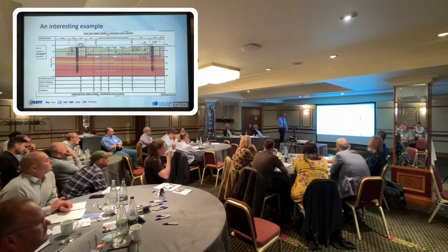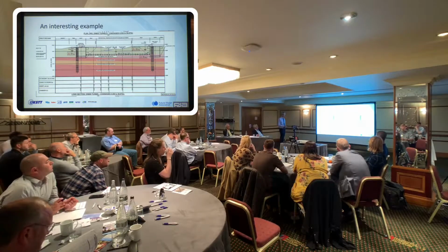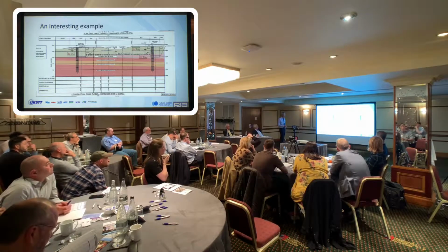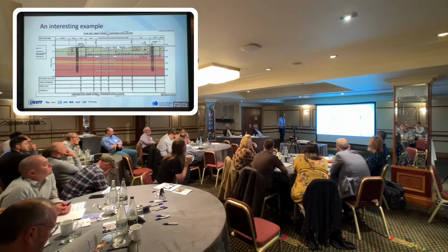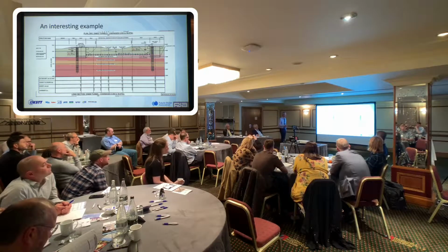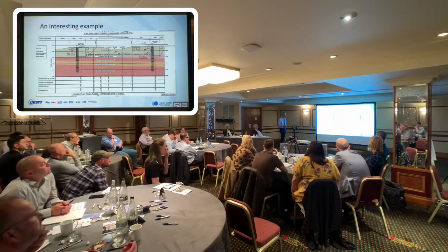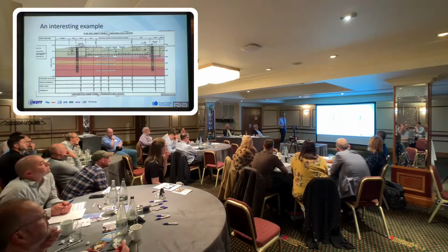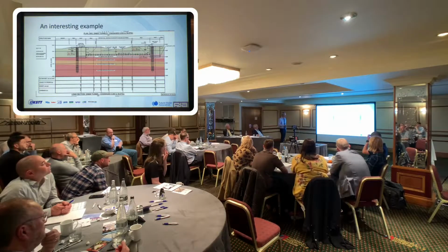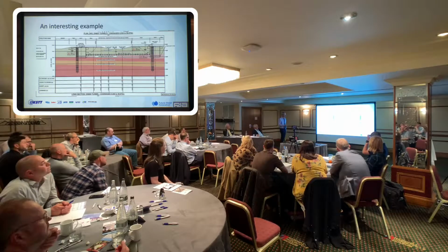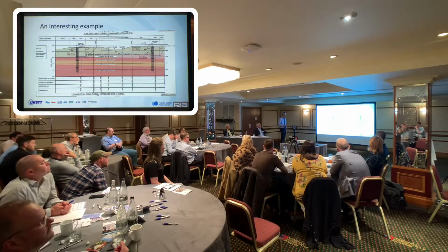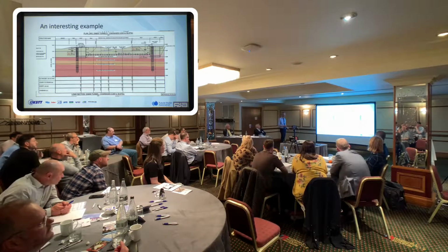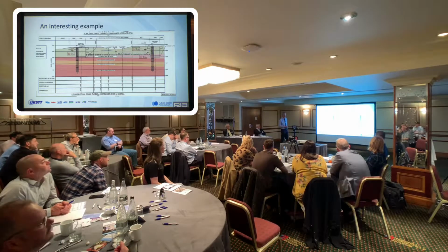It's not particularly a bad tunnelling material, but it's not the best. And then underneath that we've got weathered mudstone on top of mudstone on top of a band of very hard siltstone. So we've got high water table, very hard material, and the constraint of settlement on the railway. Now, in order to put that shaft down and get through the siltstone to get into the mudstone as a tunnelling medium to minimise the settlement, we've got to deal with the water.